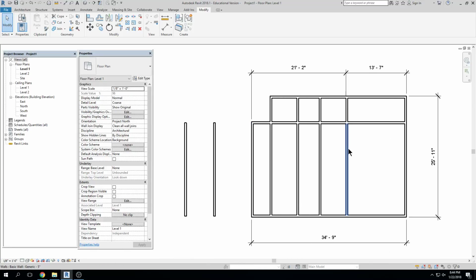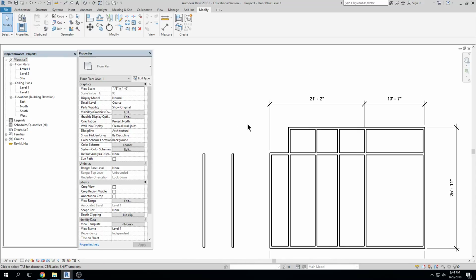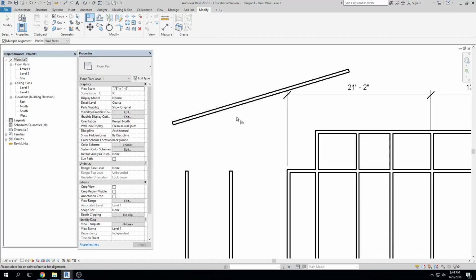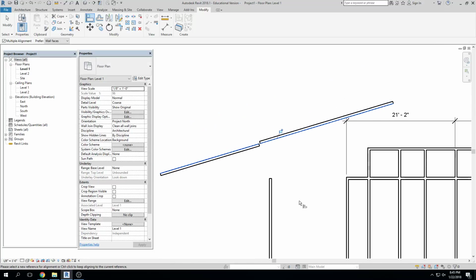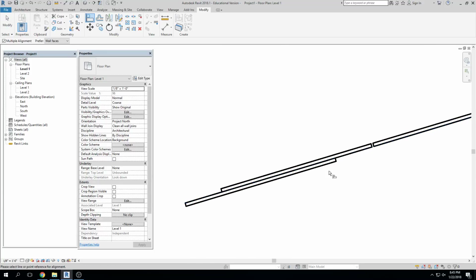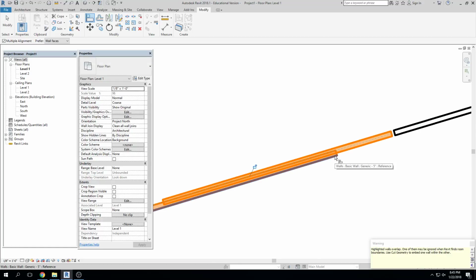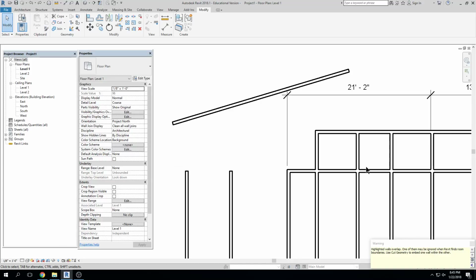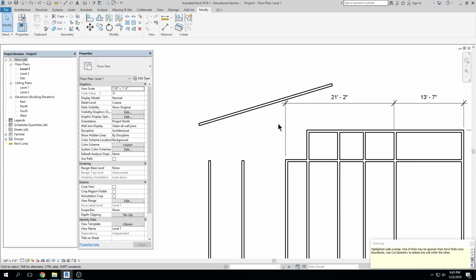You can align anything to anything else, right? We're going to start talking about reference planes in a little bit. If I have a specific angle, we'll use reference planes a lot, but what if I wanted them all to align to that angle? AL, click, and they align. Oops, well, they are offset. AL, click, click, there we go. AL, click, click, there we go. AL, there's the center point, click, center, now it's going to freak out. They're overlapping, right? Undo, Control Z, Control Z, Control Z. I'm undoing.